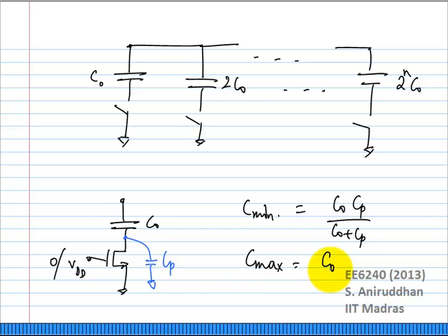As it turns out, there is a trade-off involved here too, because the larger I make my switch, the better the series losses, because the switch will have some series resistance, which will lead to series losses in the capacitor bank. And remember, the more switches you turn on, the more capacitors, the larger capacitor you want, the series resistance also increases proportionally.